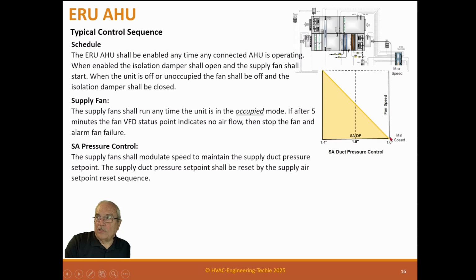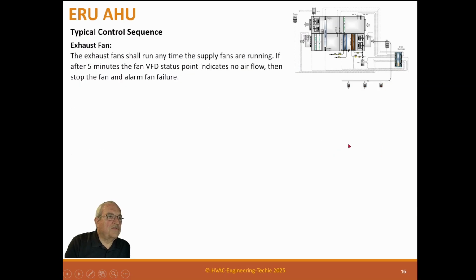At 1.6 they'll be down at low speed. And of course these depend on what the TAB set point currently is. And remember, normally it'll just work right around there. Exhaust fans. The exhaust fan shall run anytime the supply fans are running.